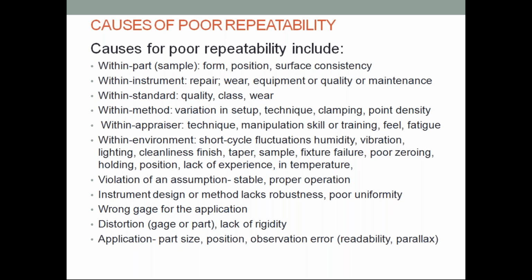For example, within part. Are you moving around a part instead of checking one part? Hey, if you are capturing roundness because you're not measuring the same place over and over again, that's not the gauge's fault. You don't want to include that as a part of your gauge analysis. You just want to know if that gauge can measure that characteristic.